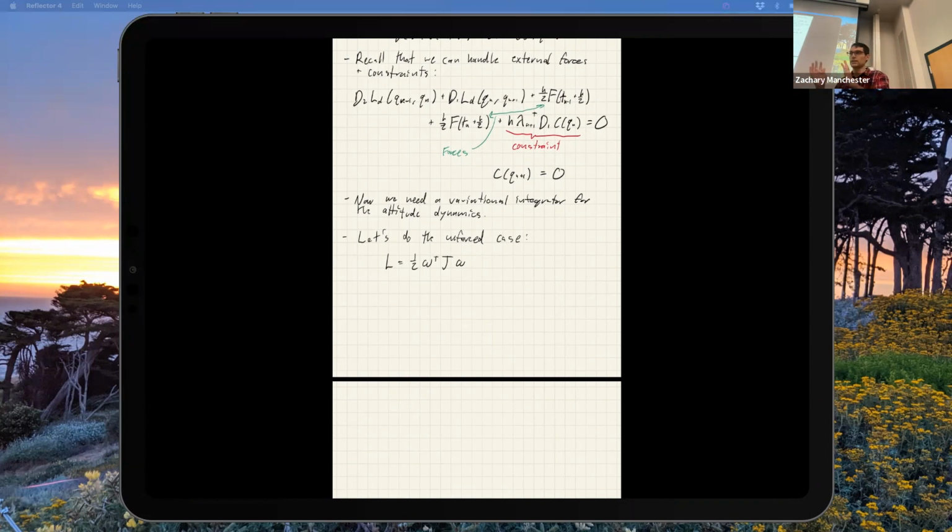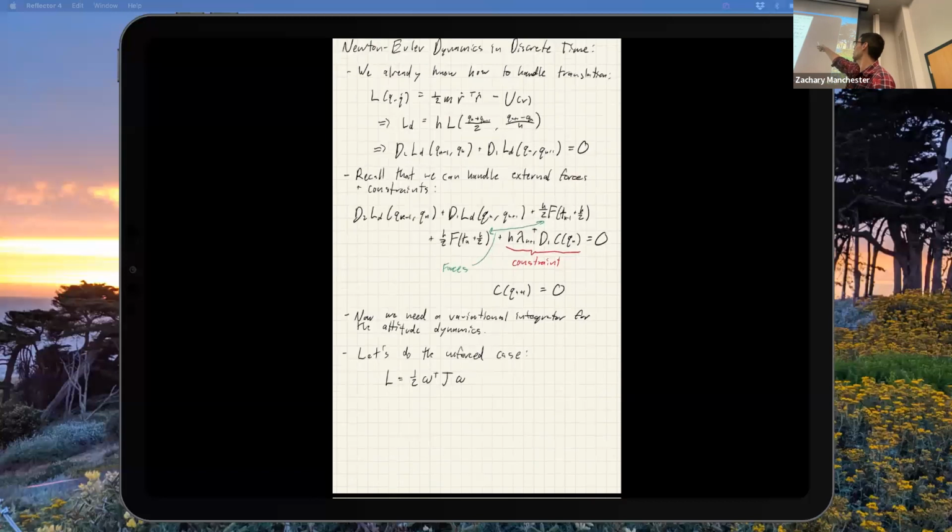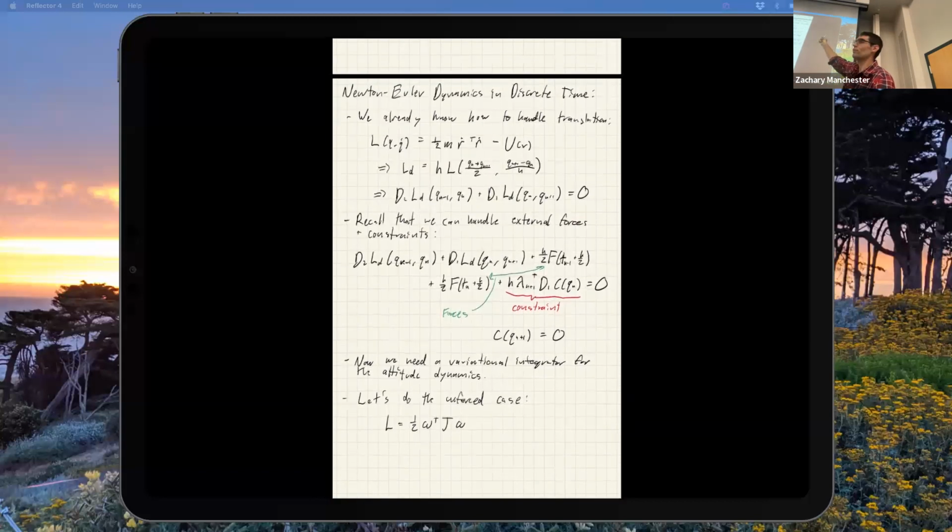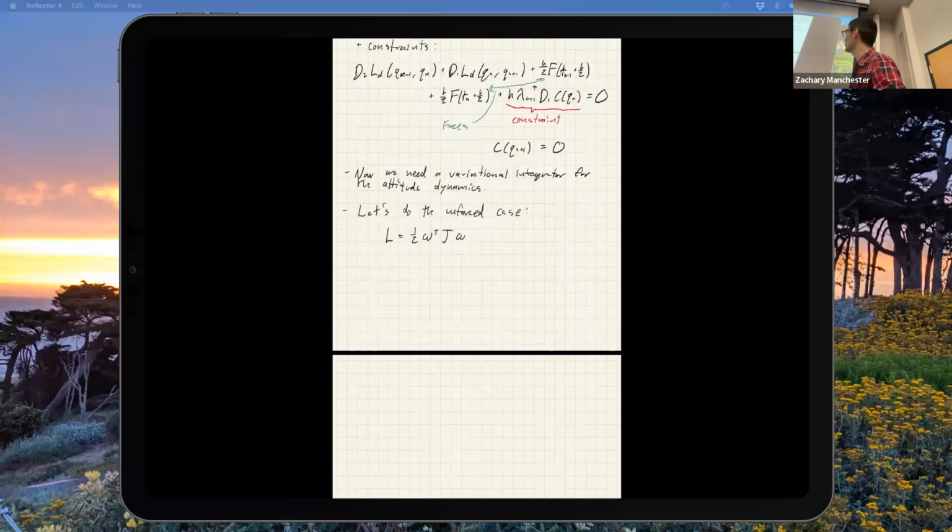Just like in the position version, we're going to use poses. So what we need to do is finite difference quaternions to get a finite difference omega approximation. Up here, we just subtract and divide by a time step, and that's all good. But I can't do that for the quaternions. Subtracting them is sort of not legal. So we're going to do it a slightly different way.